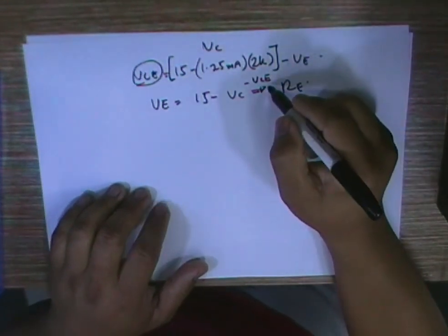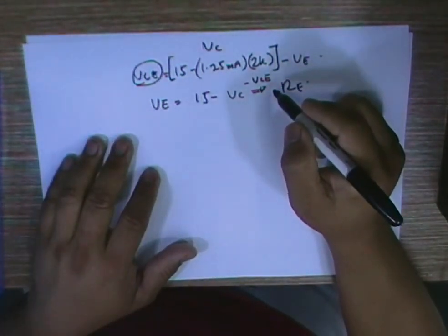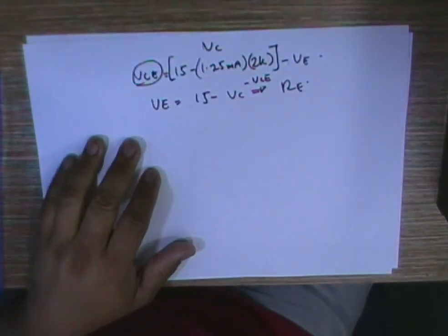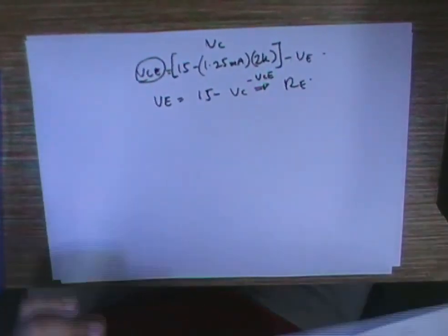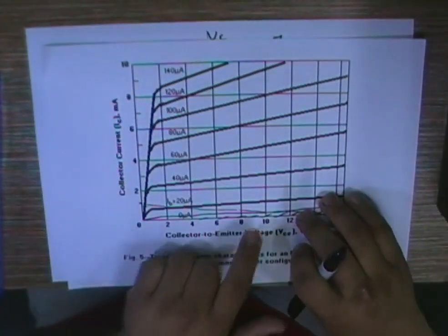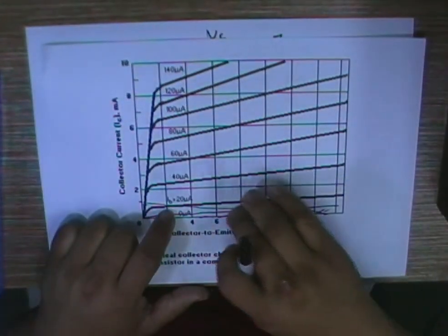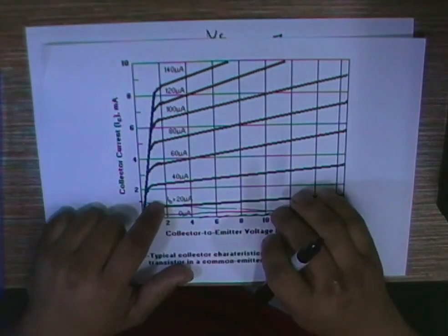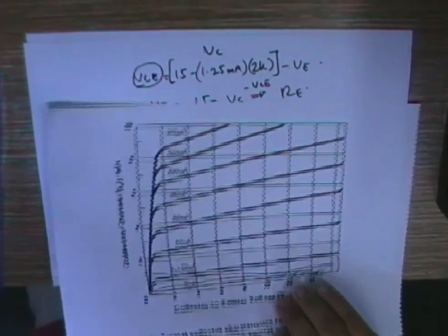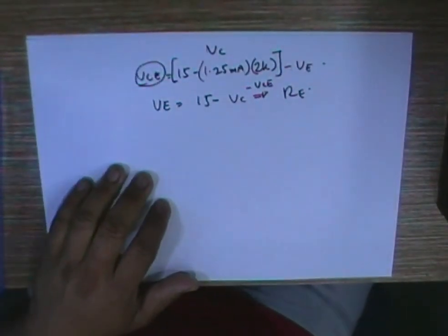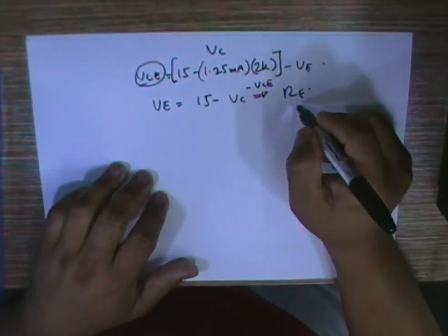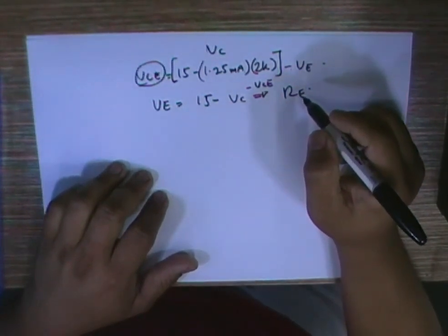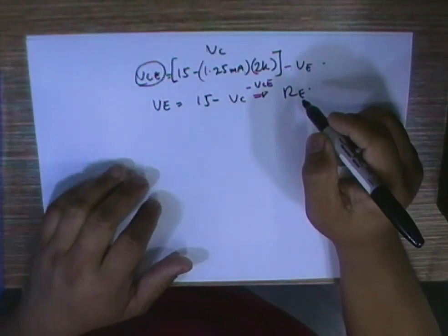if I set my VCE to be very high, 2/3, then you can see that my amplifier will easily fall into the saturation region. If I set my VCE to be very low, less than half, even though it has a high swing, you can see that my transistor easily switches off because I do not get the basic requirement of the full swing.